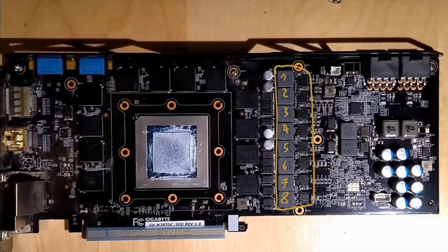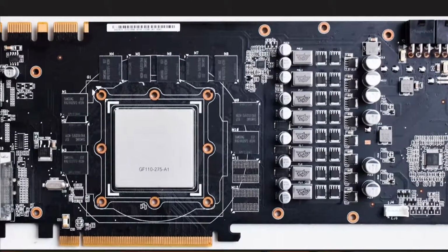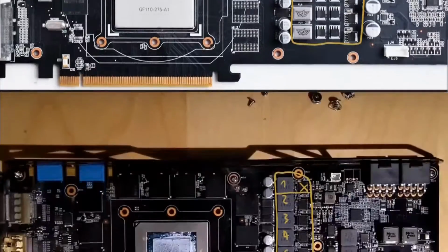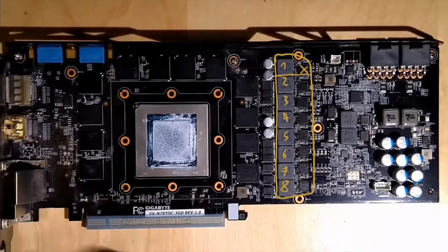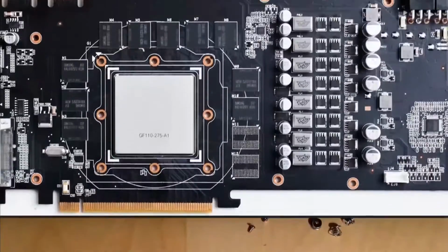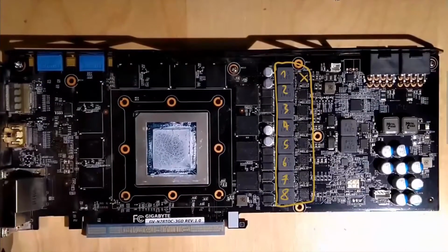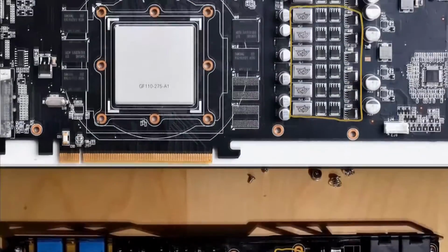The thing I want to say is you have this one inductor, and then you have one power stage, and that's one phase. And then over here it looks quite different, because this VCore VRM is a lot bigger, and this is actually a 6-phase. It is not an 8-phase, because actually I got this wrong, because this is the VCore VRM. Those two phases up there, those are VMEM, which is this right here on that card.